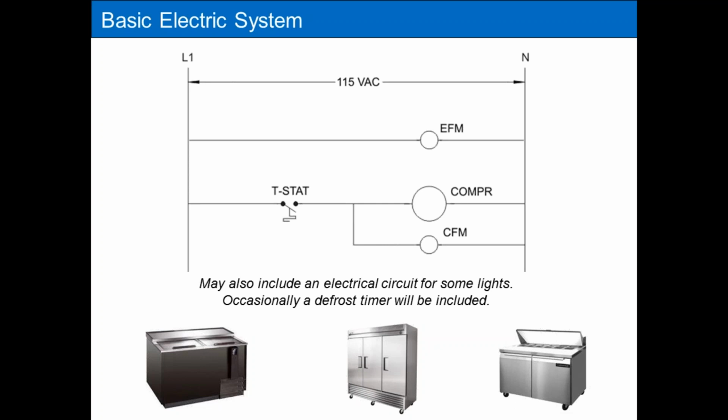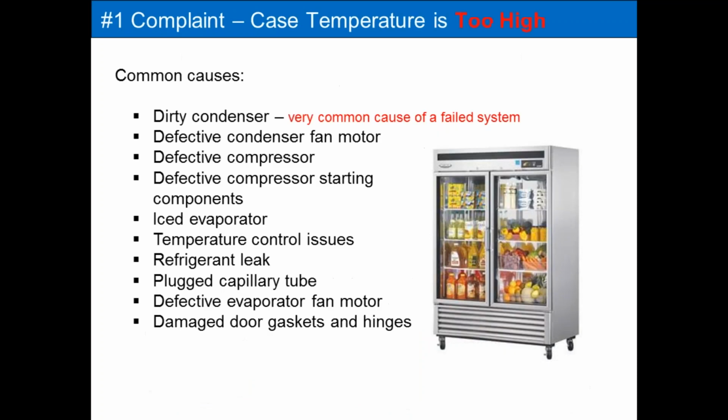Now, included in some of these electrical systems, you may see some lighting systems, a general lighting circuit, and every once in a while too you'll also see a defrost timer. A manufacturer will design their system to mechanically shut off the compressor by time to assist the defrosting of its evaporator. So you may see some wiring diagrams with a defrost timer included. But what I'm showing you on the screen is by far the most common wiring scheme out there. So let's get into troubleshooting.